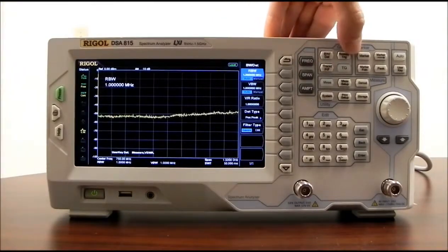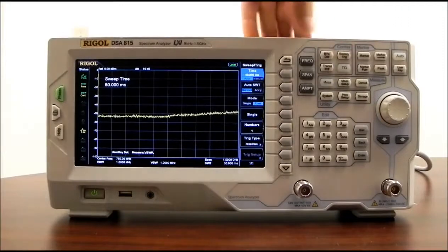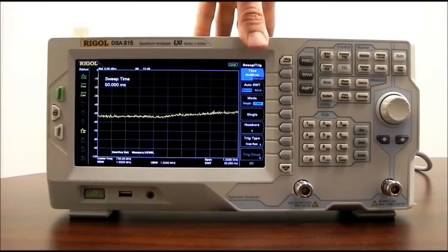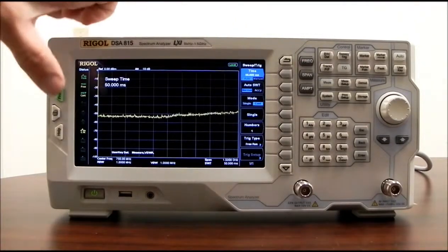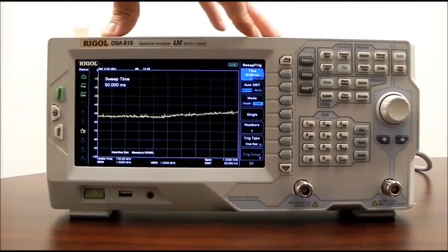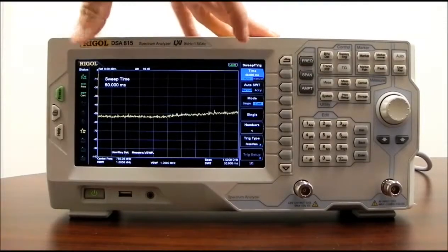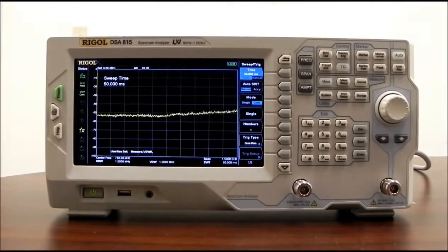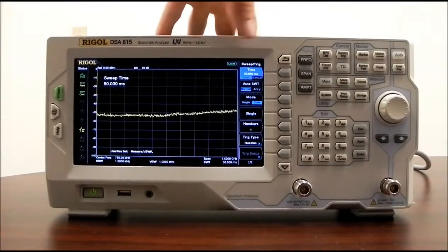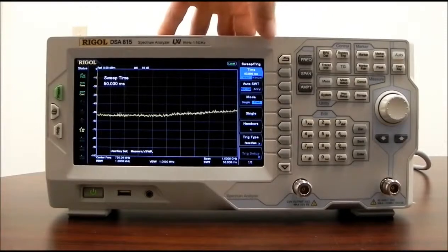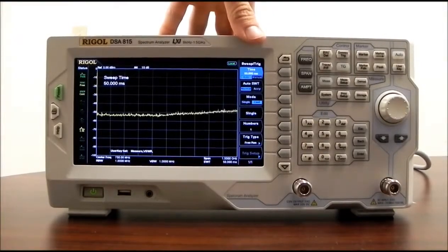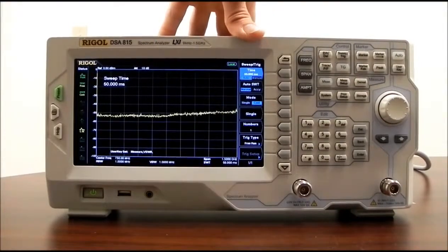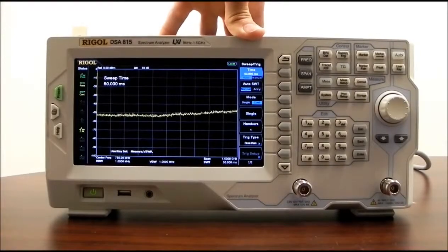And now let's take a look at the sweep and trigger. We can see that we can set the sweep time. Typically that sweep time is going to be on auto, and it's going to be based on the amplitude and the sweep configuration that we have set. The frequency range, the span, and the resolution bandwidth are going to determine that sweep time if we're in auto mode, and that's going to be calibrated. If we go to a manual mode, it's going to be uncalibrated because we're actually forcing the box to do things that it's not necessarily optimized to do in a calibrated sense.